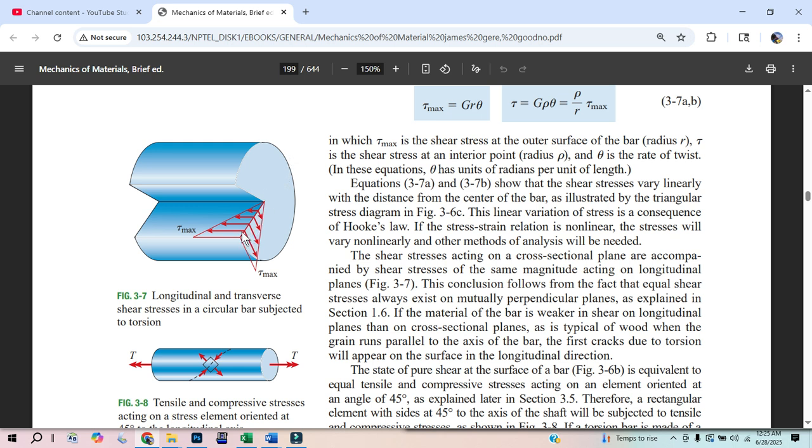Like 180 degrees is the circumference divided by 2, times 360 degrees in a circle. You know what I mean? So there's a lot of ways. I think it's very useful to do circles a lot of different ways. But anyway, you're going to have that 4 millimeters divided by the circumference times 360 degrees. That'll give you the degrees of rotation.